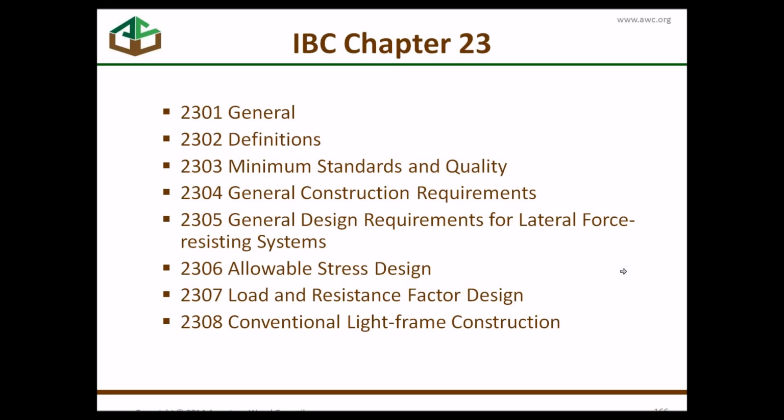This is traditional conventional construction and framing techniques from many years of very practical experience. The scope of that section, 2308, one of the major limits is a 40 pound per square foot floor load. It has limited applicability in commercial construction.